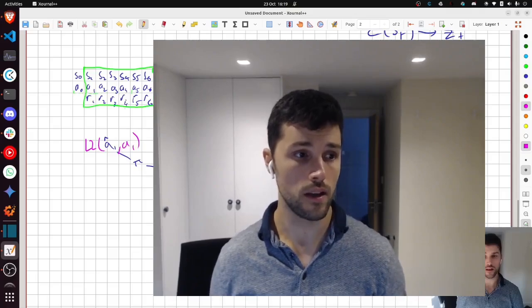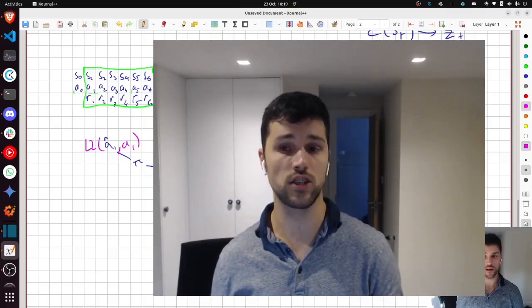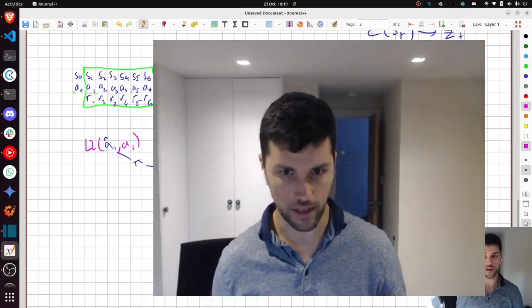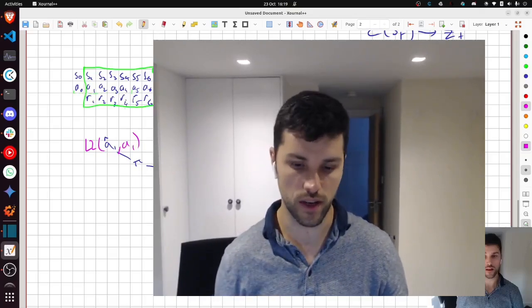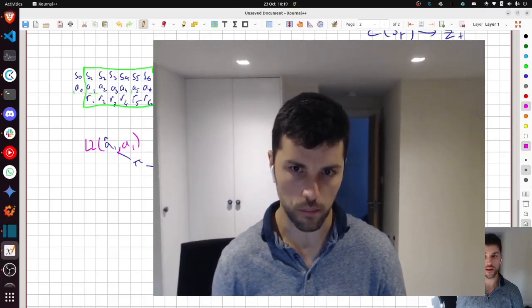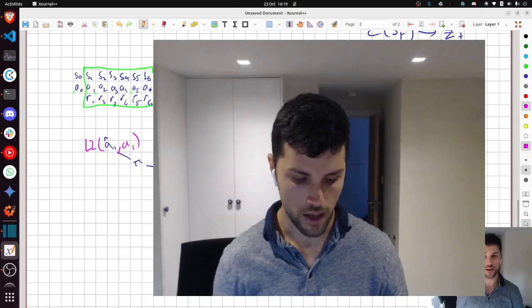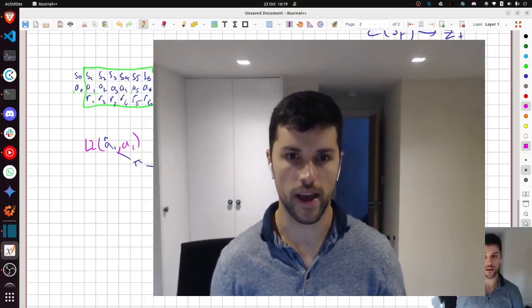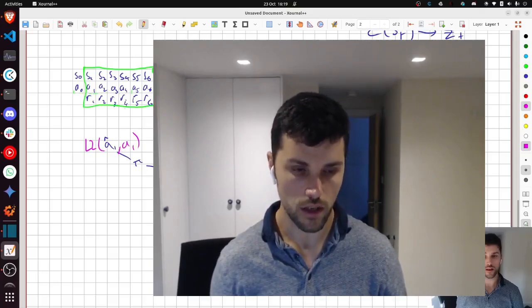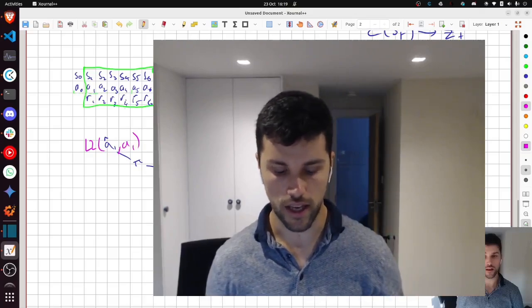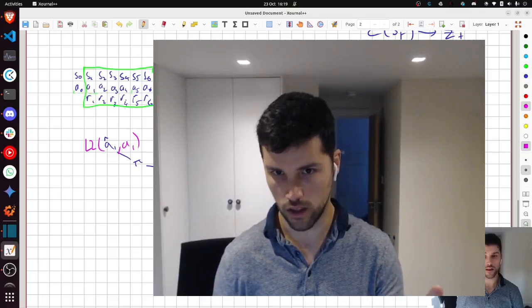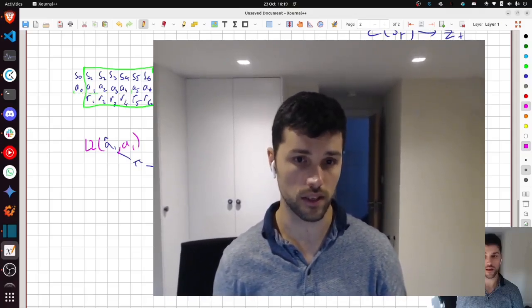This was the network that takes in as input the state and the action and gives you an estimate for the future return of the whole episode. So in TD-MPC, the idea is to pass the action to the Q network, and what you end up trying to do is maximize the output of the Q network. It's probably more nuanced than that; you should look at the paper. In another flavor of TD-MPC, which is the one I actually implemented in Hugging Face's LeRobot, they do what's called advantage weighted regression. So each action is weighted by how good we think it is, and how good we think it is is based on the Q network and also another V network, which I won't get into details right now.